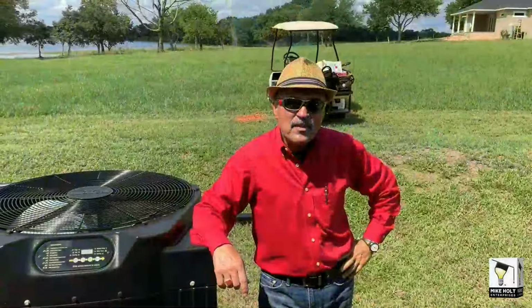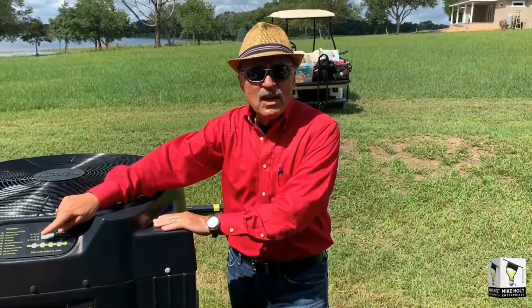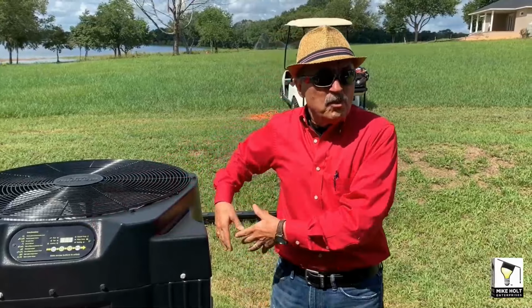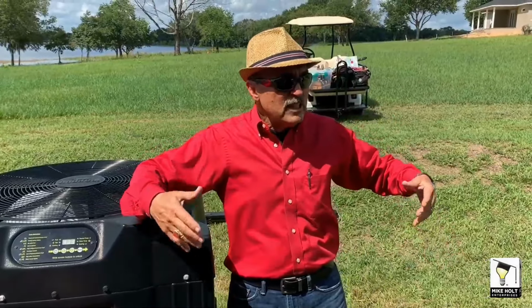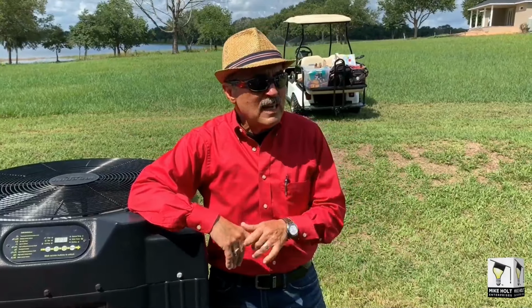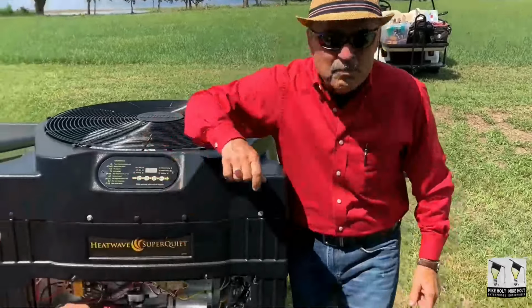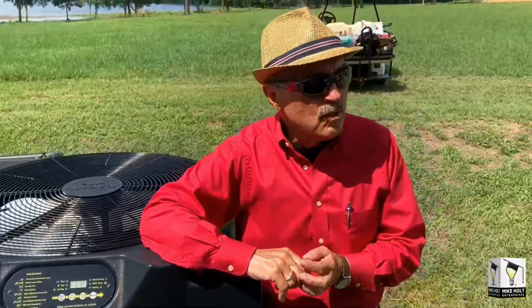Okay, so we see that grounding equipment and not providing an effective ground fault current path is not going to clear the fault. Yes, you do have some current traveling, and yes, you do have a voltage gradient, so you've expanded the area to kill somebody. You never ever drive a ground rod except where it's required by the National Electrical Code. You always bring an effective ground fault current path to every piece of metal that's connected to equipment.